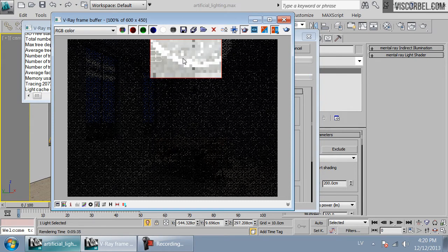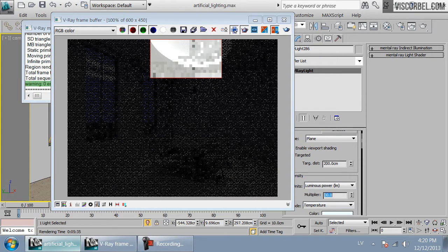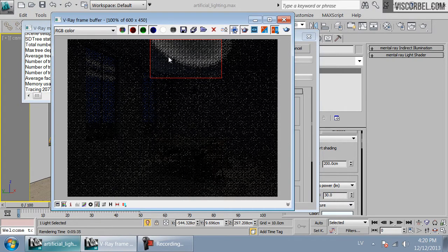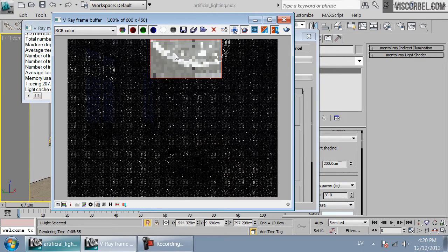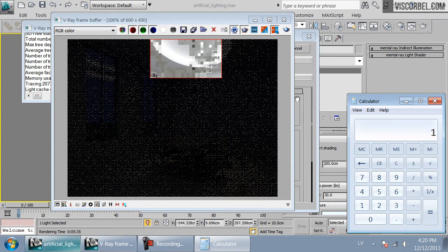And right now it kind of looks much too bright. So let's bring down the luminosity to maybe, I don't know, 30 lumens per light. Since there are so many of them, you can actually calculate the total lumen output. Let's say 120 by 30 lumens, that's 3600 lumens of light for this whole area. I think that's not too bad.